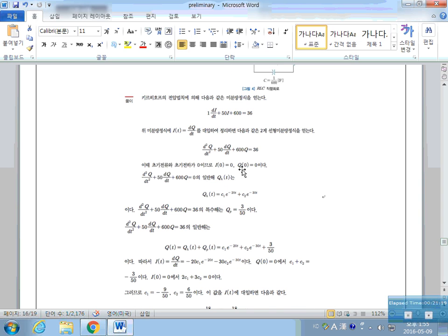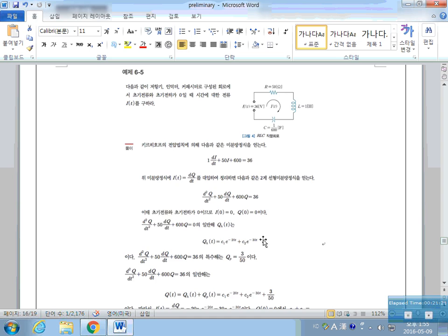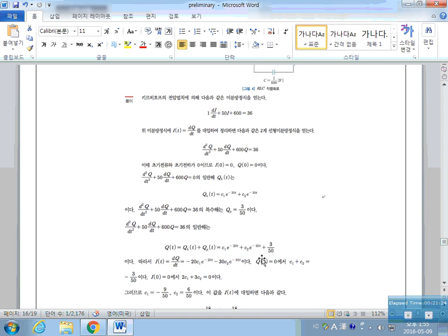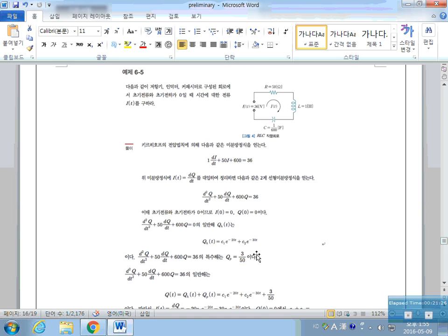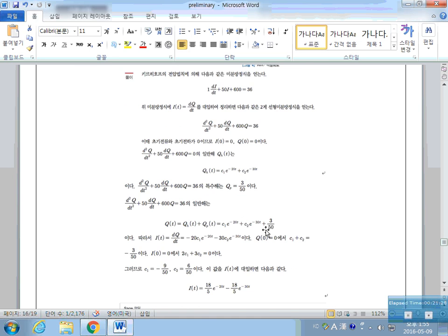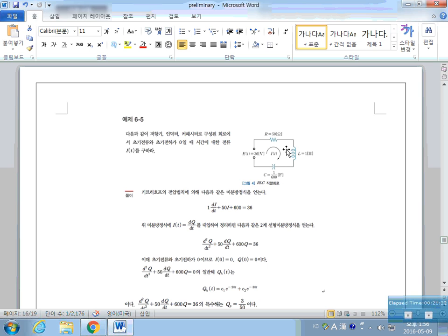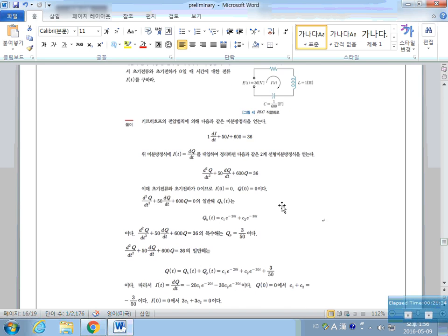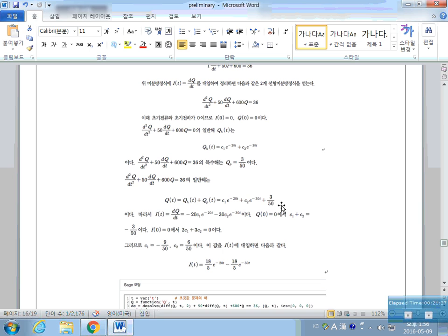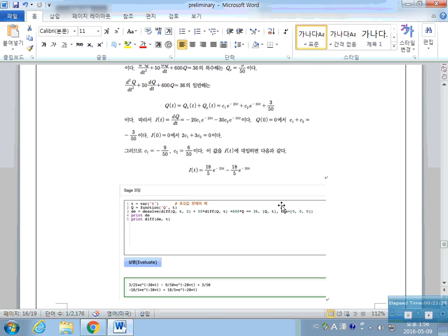You'll notice that solving this equation and finding the current is a little bit complicated for a very simple circuit like this. That is because we are trying to use differential equations and integrals. However, commonly we use either the frequency domain or the Laplace transform to find the ordinary differential equation solution, just like what Naim said in the solutions for differential equations.